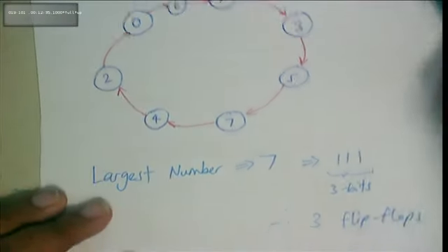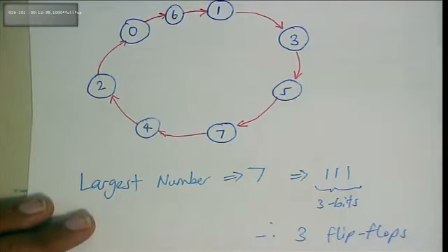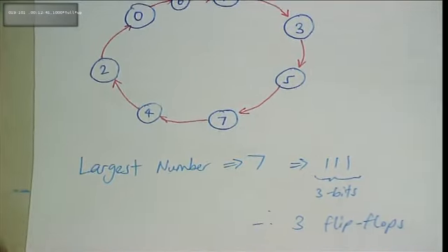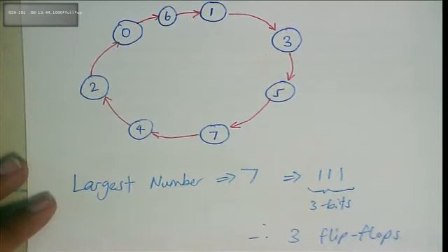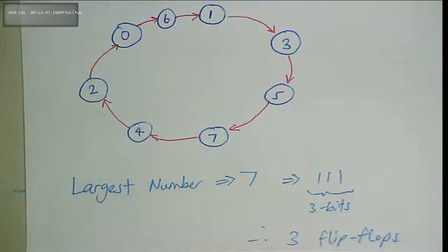All right. So let's now translate our particular ring counter into binary. That's the next step. Right now, we're just showing what it wanted in decimal. Right? And there's no control. Remember, there's no control. In your project, there's a control. So if x is equal to 1, it's going clockwise. And if x is equal to 0, it's going anti-clockwise. So you've got to accommodate that in your state excitation table. But over here, there's no control. It's just going in one direction continually. So we're happy with that, all right?